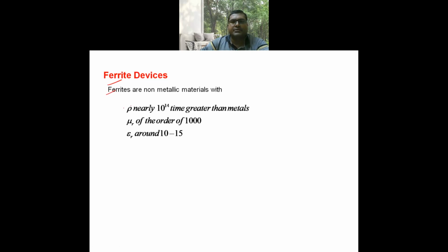Ferrite devices. Ferrites are non-metallic materials with resistivity nearly 10 power 14 times greater than metals, permeability mu of the order of 1000, and relative permittivity, or dielectric constant, around 10 to 15.